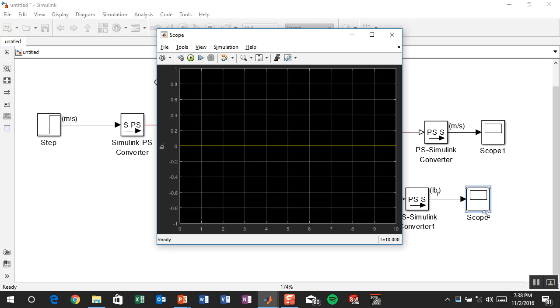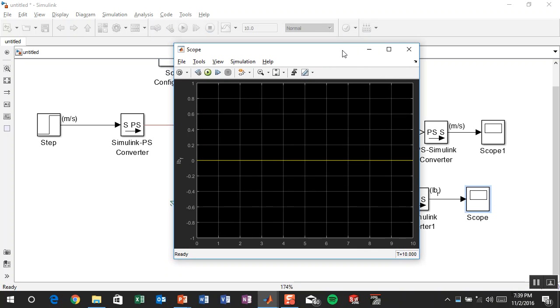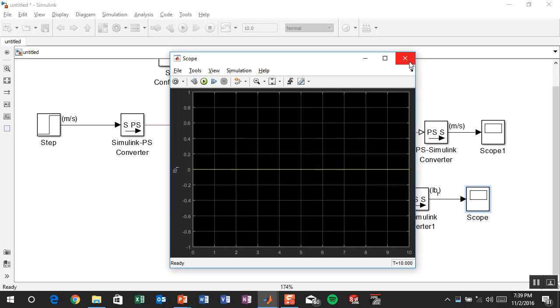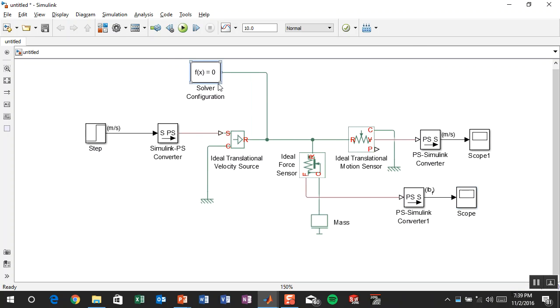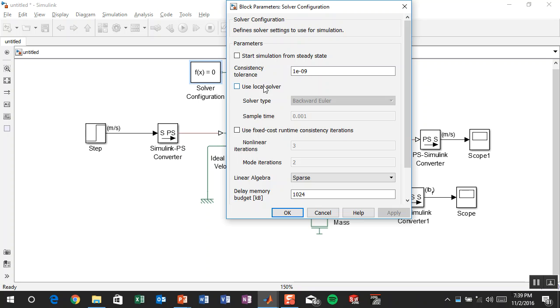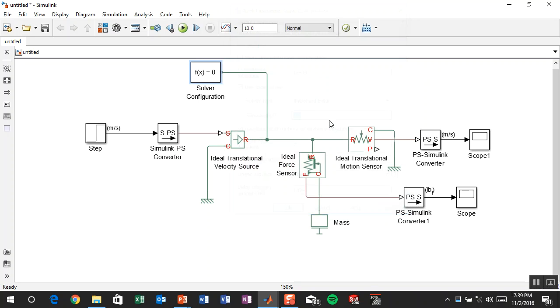It's not a trick. I mean, this is what it actually solved. I actually called MathWorks support about this because this doesn't make any sense. Tech support guy said, "Yep, that doesn't make any sense to me either." So apparently, it's a bug with their variable step solver. But it does kind of give us an interesting reason to try the local solver. So we'll click on use the local solver, and we'll just give it 1/10 of a second sample time.